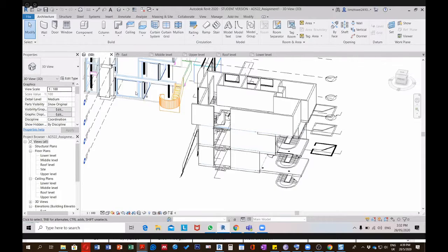Share your screen, please. I did this wall over here, 1, 2, and then this one, but I don't know how to put the walls for the interior part. I did put the walls for these 3 places only, and the interior side I didn't put because I don't know how to change the size. Thickness, you mean? Yeah, the thickness. It's easy, and it's in the video that I gave you, and it's in CN. You have to watch the videos also.